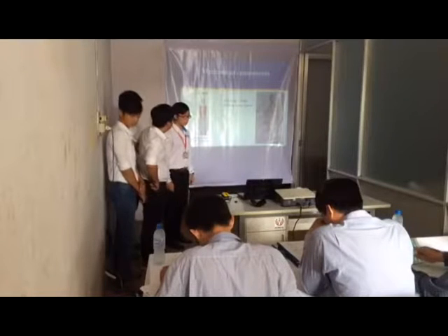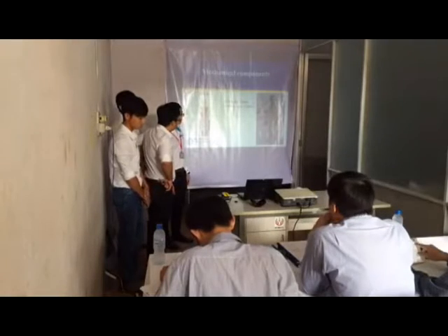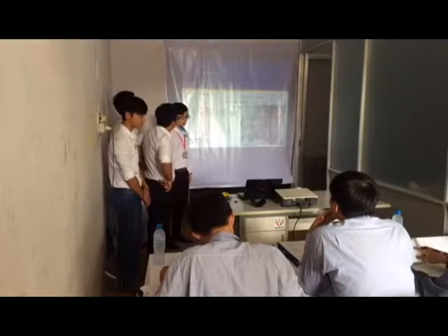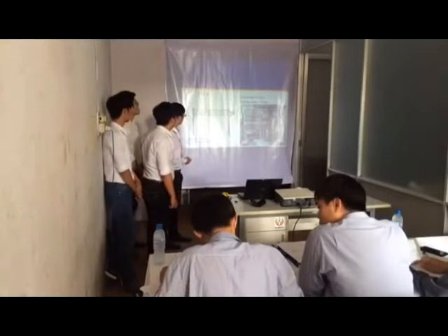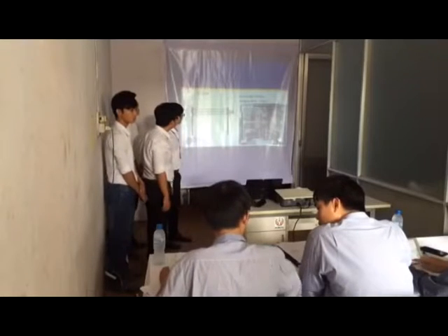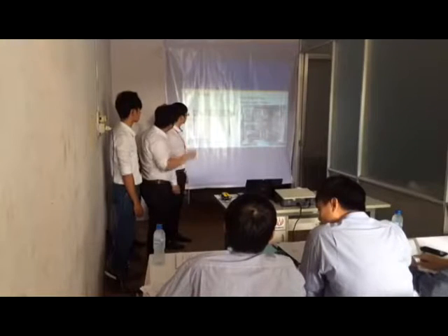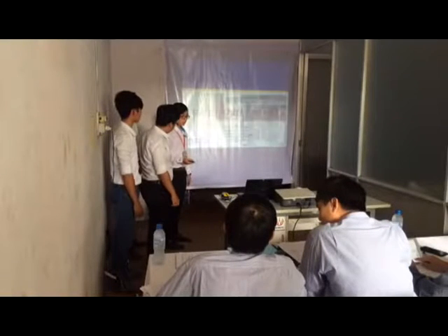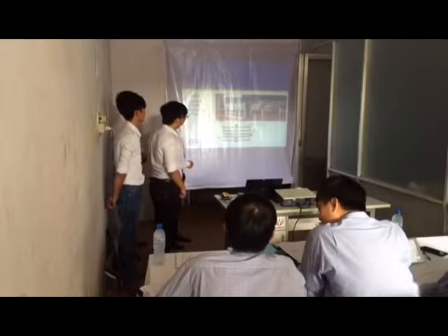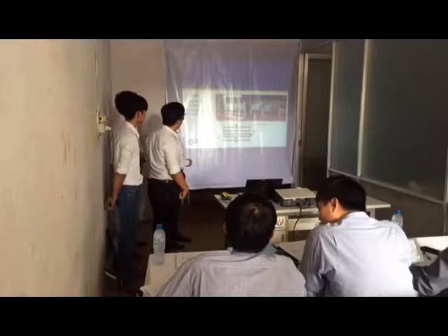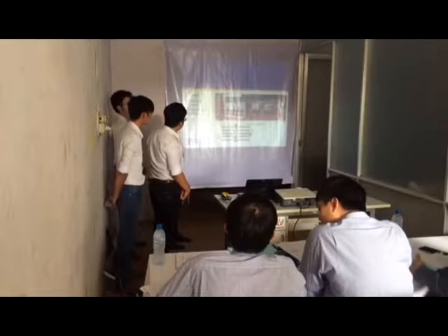This is the Y axis with a total length of 320 mm and a working stroke of 210 mm. And this is the second axis with 2 guide rails and 1 lead screw, with a total length of 692 mm and a working stroke of 554 mm. And the last axis has 2 straight motion rails and 1 lead screw, and its total length is 1255 mm and its working stroke is 1000 mm.